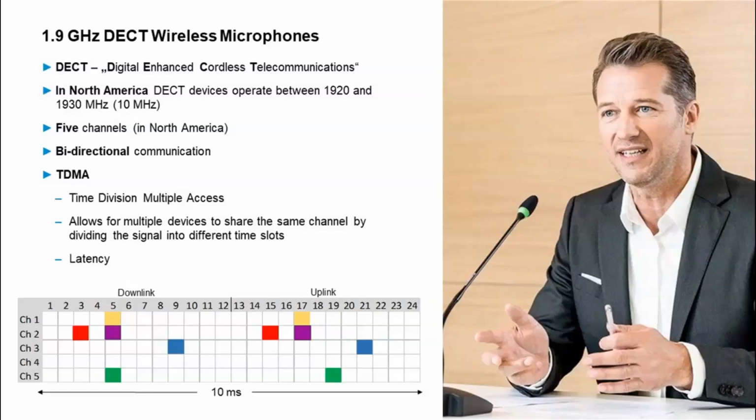So we looked at the analog systems, and we know that we have to coordinate for intermodulation and things like that. In a DECT system, it uses something called TDMA, or time division multiple access. And what will happen is one channel will stand up, and as the other channels are turned on and activated, they'll check in with that first channel as secondary channels, and they'll automatically find time slots to operate in to stay out of each other's way. So DECT is an automatically coordinating RF system.